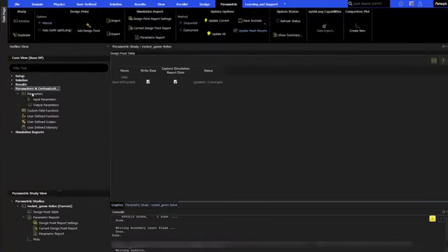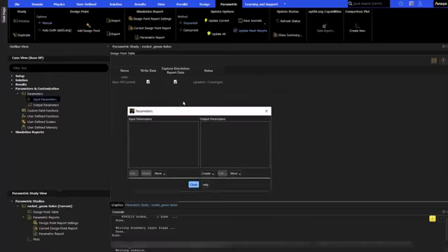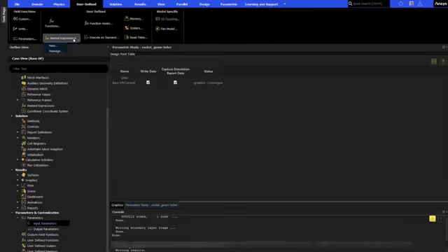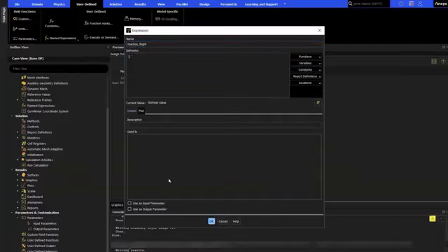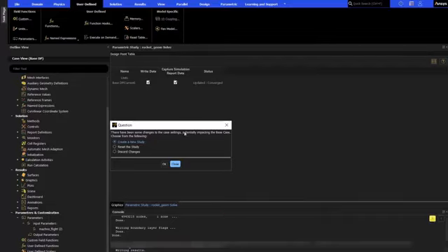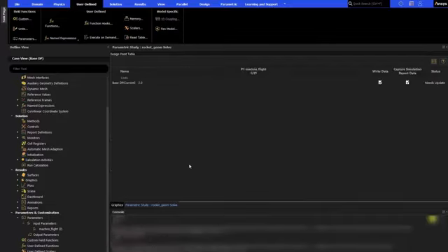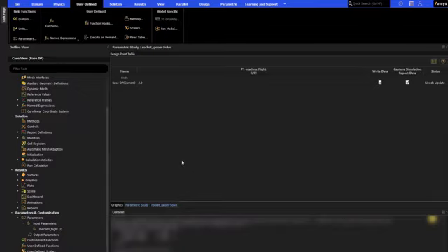A parametric setup requires both input and output parameters to be specified. To do this, we create named expressions to be used as inputs. An expression to specify the flight Mach number is created and enabled as an input parameter in the lower left checkbox. Now in the Parametric Study tab, we can see the flight Mach number specified as a variable input.